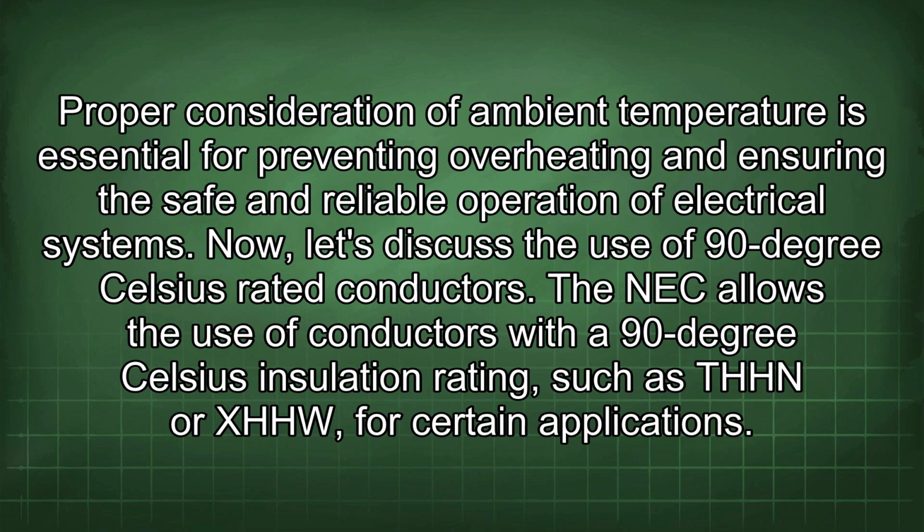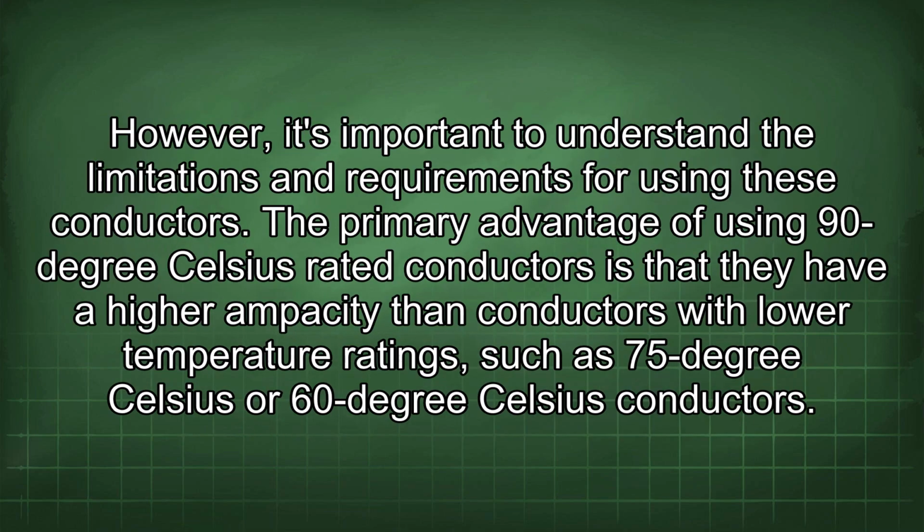Now let's discuss the use of 90 degrees Celsius rated conductors. The NEC allows the use of conductors with a 90 degrees Celsius insulation rating, such as THHN or XHHW, for certain applications. However, it's important to understand the limitations and requirements for using these conductors.